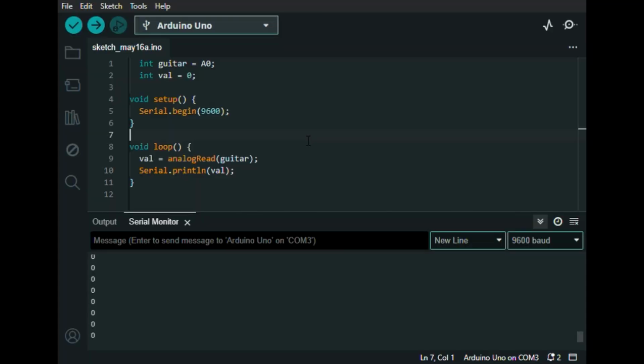So I have a few ideas on how to do this, but first let's just hook up the guitar, and I'm going to try to just uber distort it basically. I'm going to say it's 5 volts when the guitar gives a positive voltage and 0 if it's a negative voltage. Okay, so I made my Arduino code here. My guitar is in pin A0. I'm writing to the serial. I'm just printing out the analog read that the guitar pin sees.